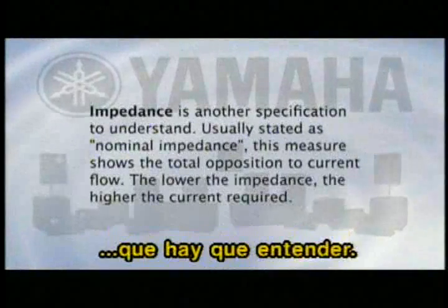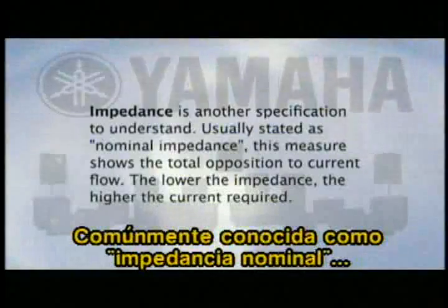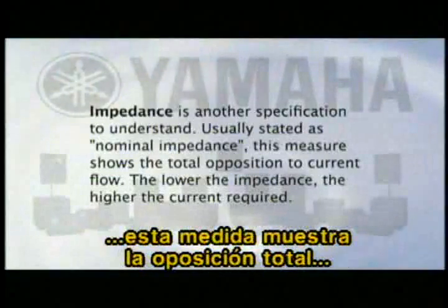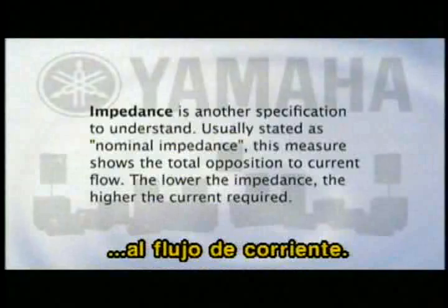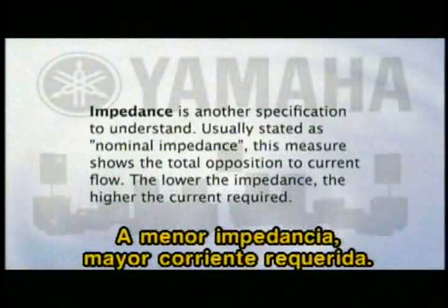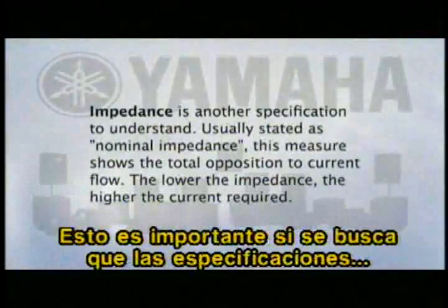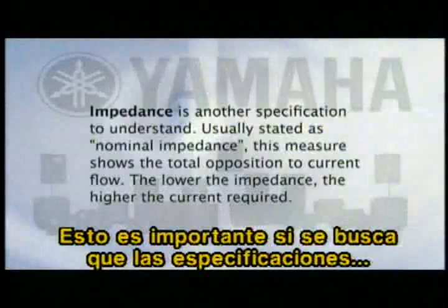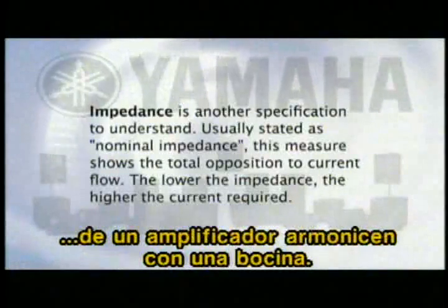Impedance is another specification to understand. Usually stated as nominal impedance, this measure shows the total opposition to current flow. The lower the impedance, the higher the current required. This is helpful when looking at the specifications of an amplifier to match a loudspeaker.